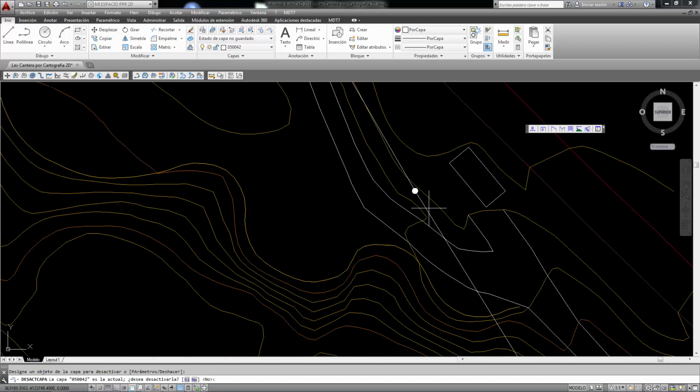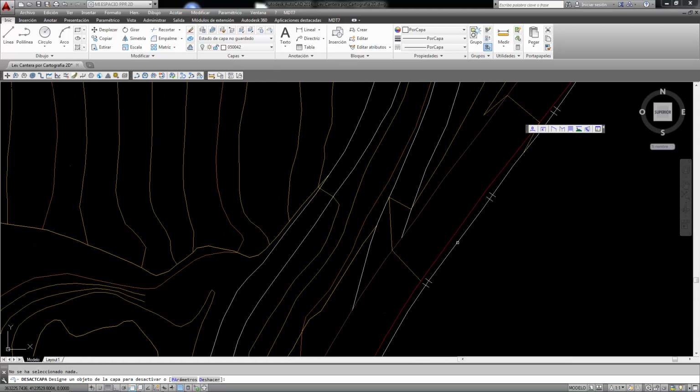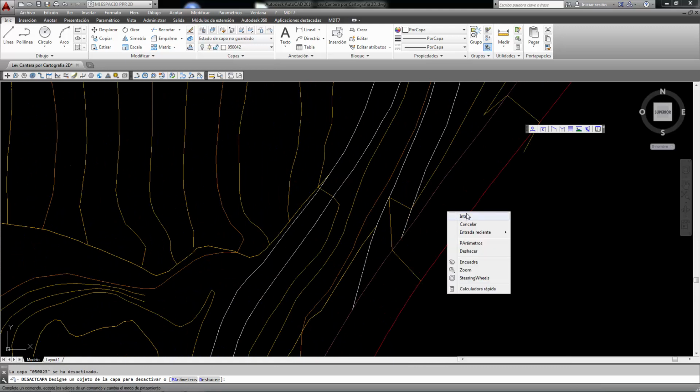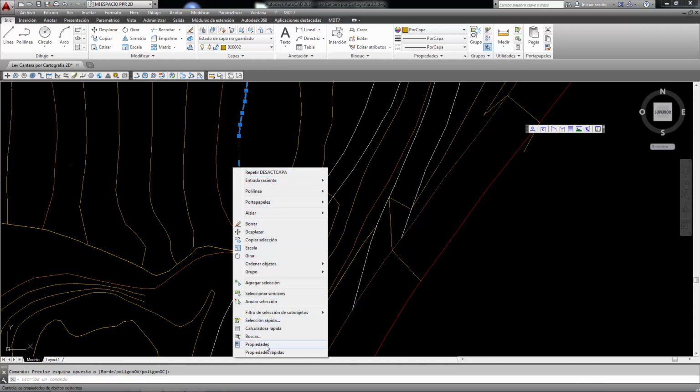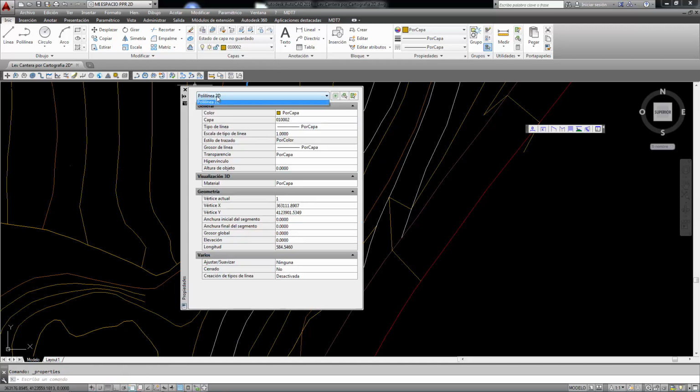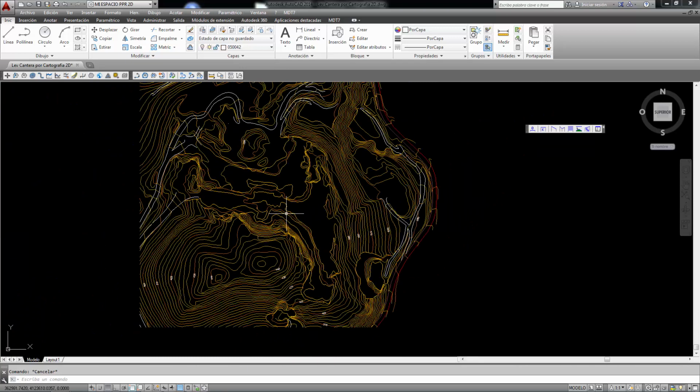These 3 Unit 4.4 videos will teach us how to obtain three-dimensional objects and the breaks for our digital model using another source of information without MDT points, as in this case. We are conducting our practical example using an old file, and as we have already seen, it is in 2D with no elevations. Let us remove the elements we are not going to use.